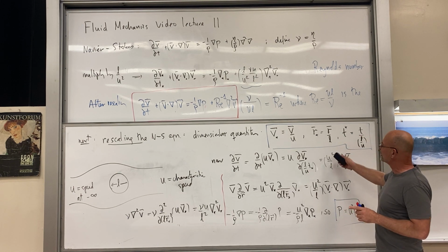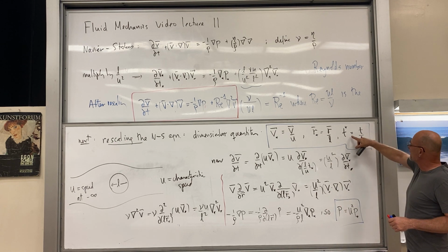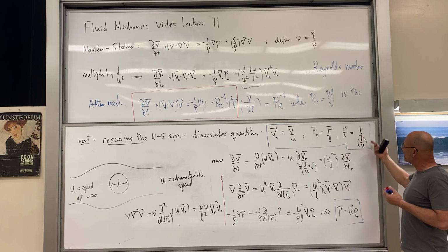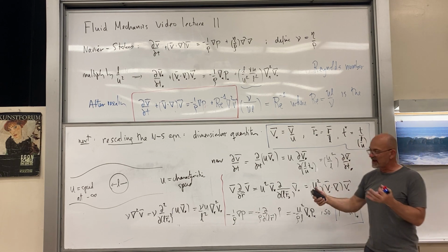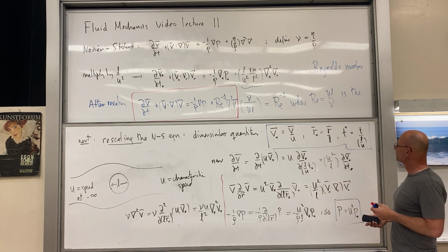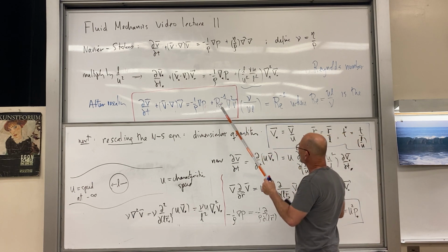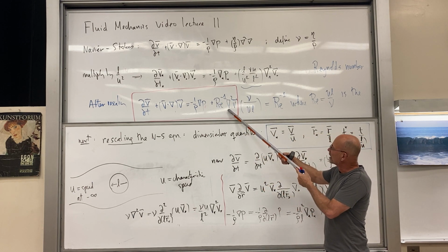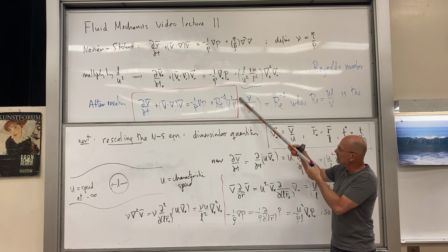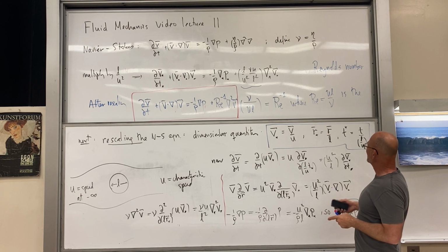And we did this systematically. There are other schemes for that. For example, instead of just scaling the time in terms of L and U here from our picture, you can bring in an independent time scale if you're talking about an oscillating system. Then you have an independent time scale based on a frequency. So that kind of thing can be done as well. But this is a good version of the whole thing. Again, when the Reynolds number goes to infinity, remember it's in the denominator here, so when it goes to infinity, it makes this thing here smaller. I'm going to keep working with that picture.